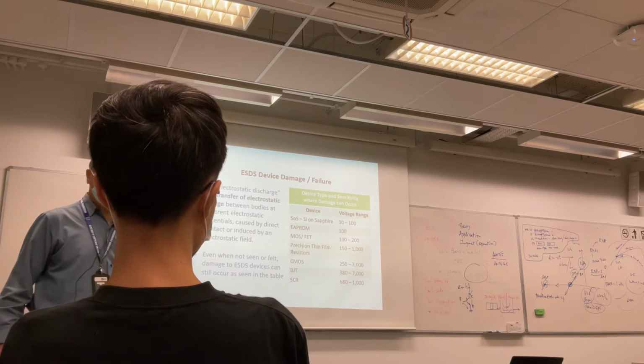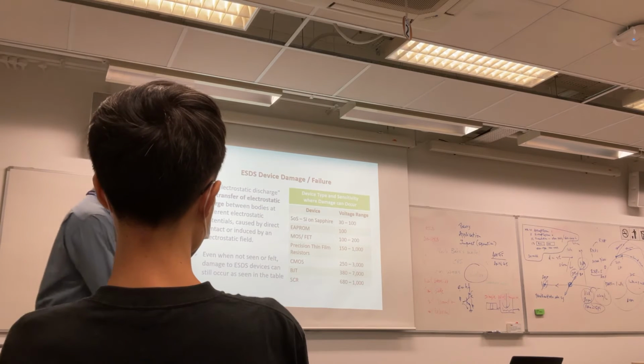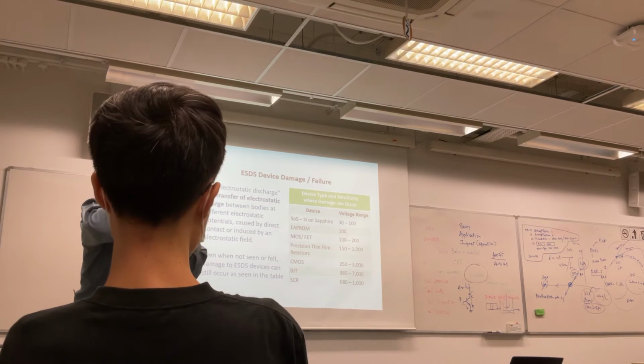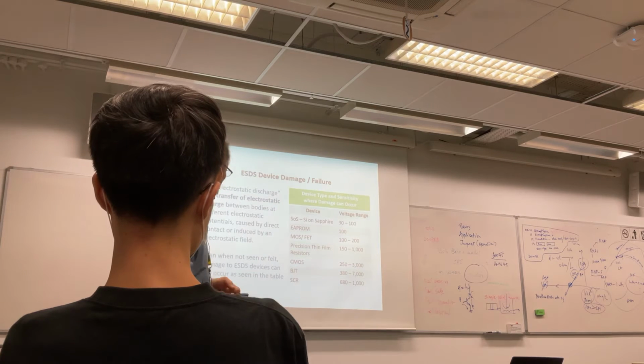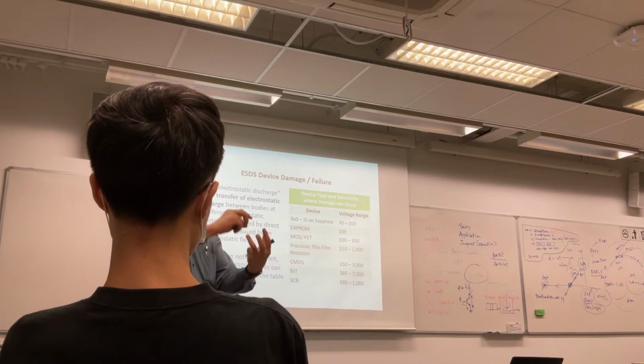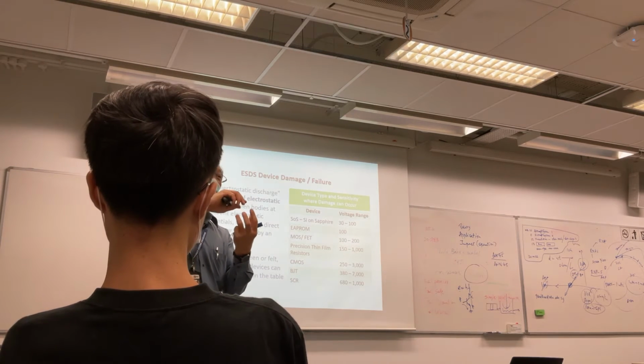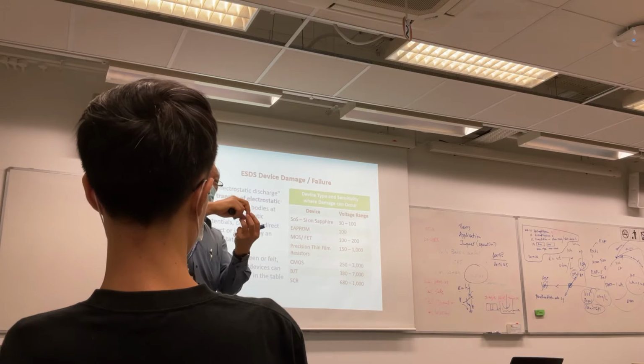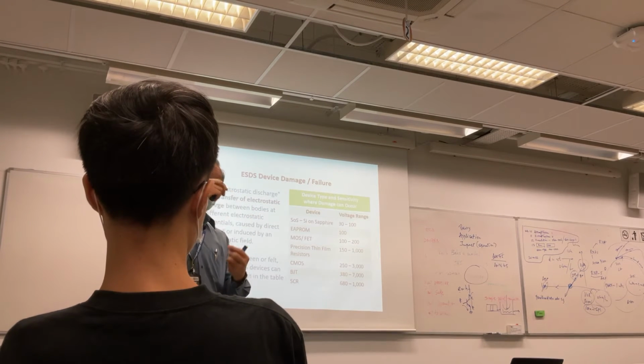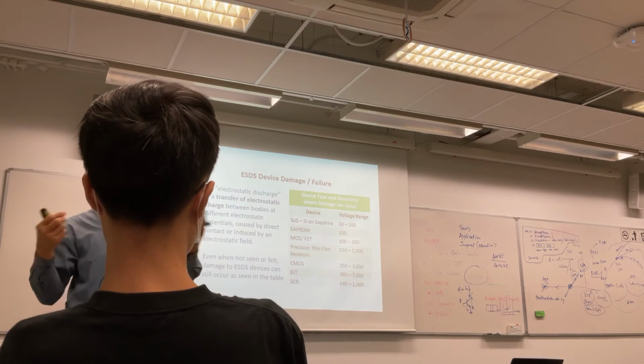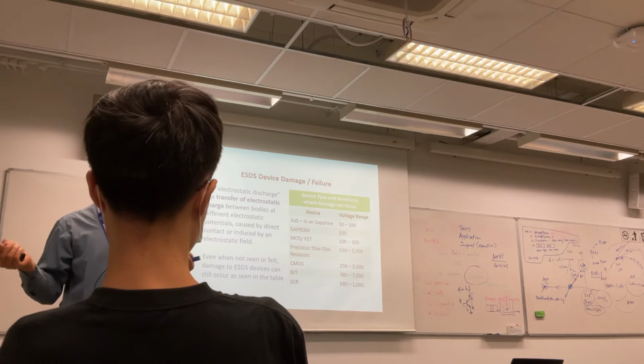So that means you handle them differently. When you buy a transistor, you just take it home and solder, no problem. But if you go and buy a FET, or an EPROM, they'll come in a black foam. So you have to put it there before you take it home. If you don't, by the time you reach home, it's gone, because your finger could cause you to zap it.